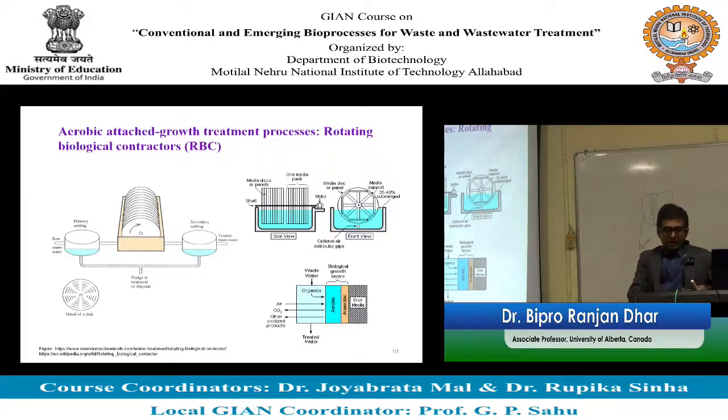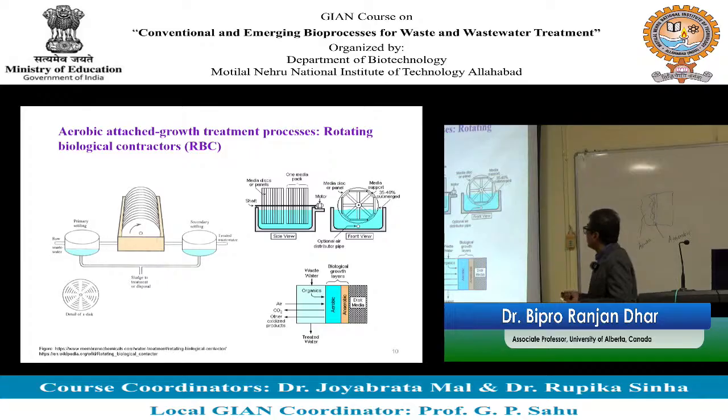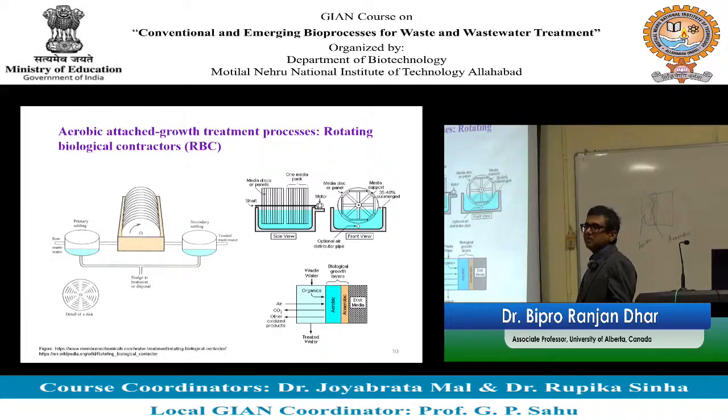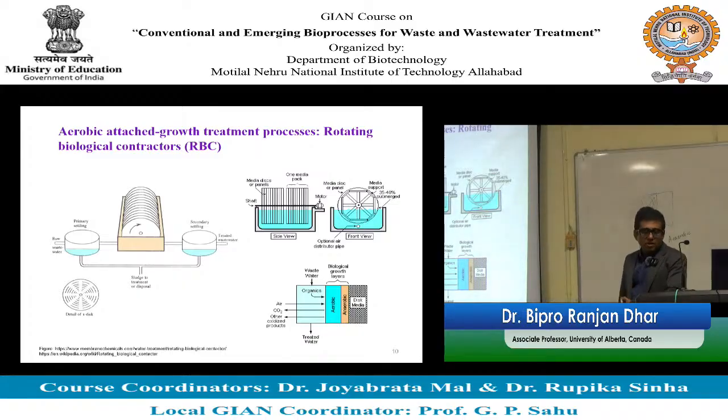So there could be this kind of situation where the inner layer is more anaerobic instead of aerobic. And typically in this kind of system you also have an optional feature for providing air, because sometimes you might not have enough dissolved oxygen, so it's better to have some option. If needed, you can aerate the tank for a certain period of time, and then you stop when you reach adequate DO level, or dissolved oxygen concentration.